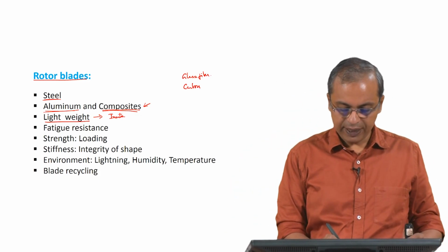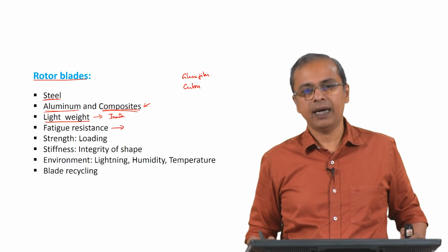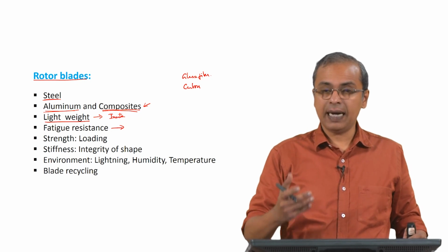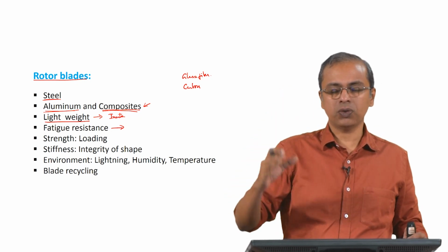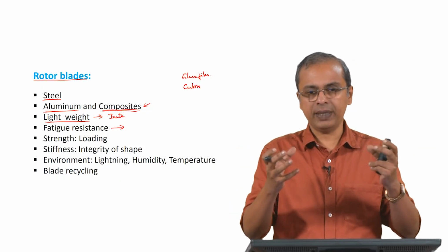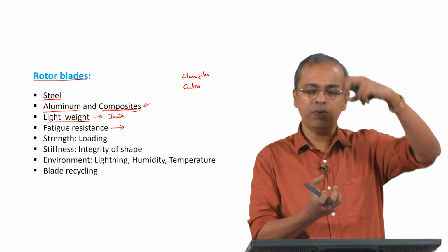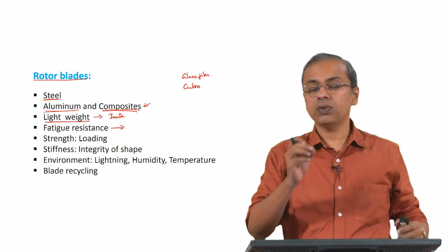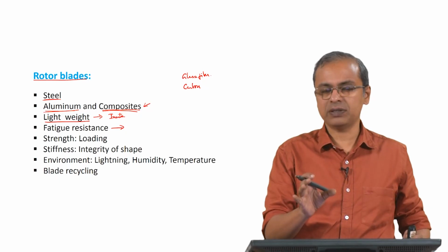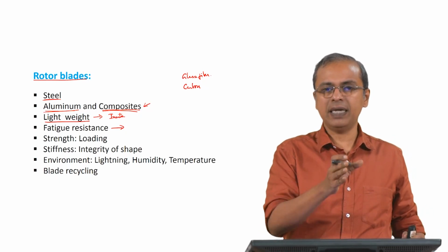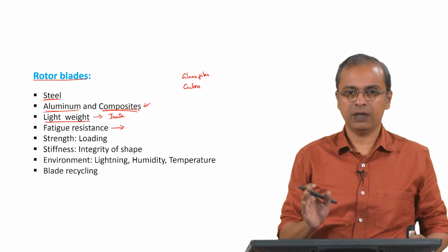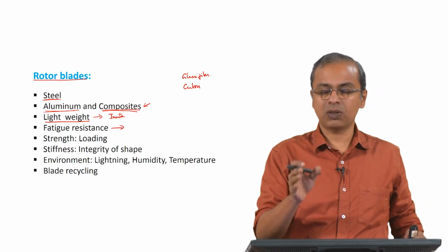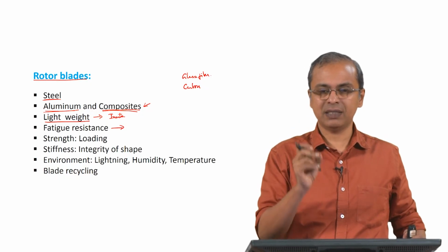Fatigue resistance. Fatigue is the idea that materials deteriorate or fail at loadings well below their rated loading. So, you take a material, make a new component, and do a tensile test. You pull it apart and see at what level of loading the material fails. Based on standard ways of testing, you can say that if you make this material with these standard dimensions, failure will happen at this load, at some specific stress value.